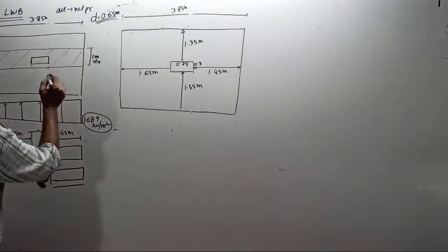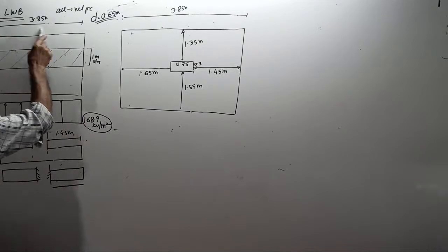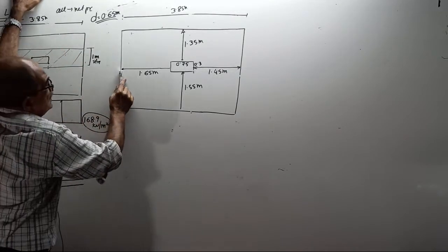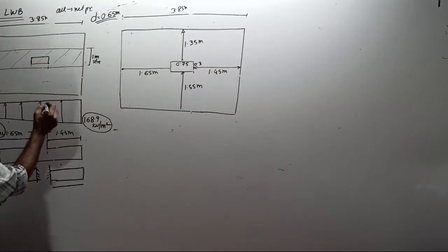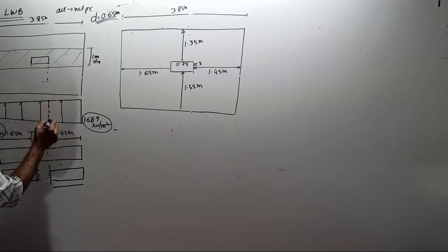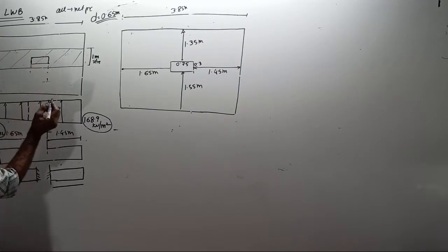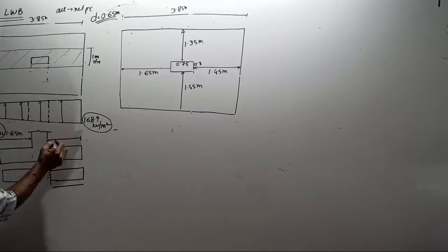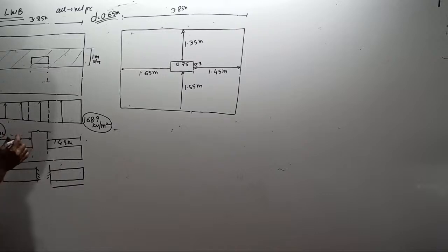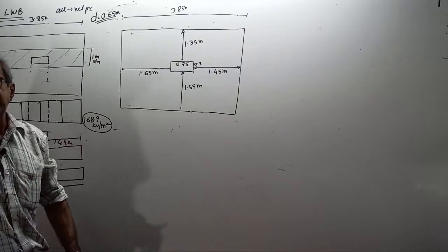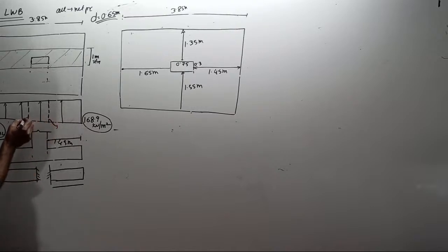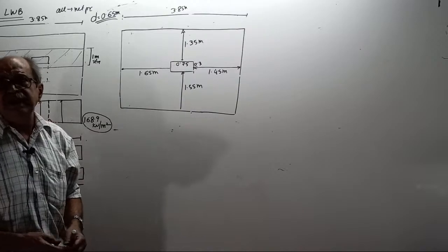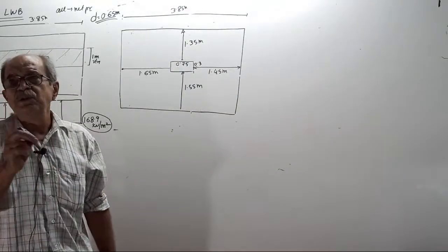Okay, now see, therefore, full length is 3.85. Here to here is 1.65. Here to here is 1.45. For some reason, I want the pressure here. I want the pressure here and I want the pressure here. These two pressures, you have to get by linear interpolation. I will use red color. Tell this pressure and tell this pressure using linear interpolation. Fast answer. This I will not explain.